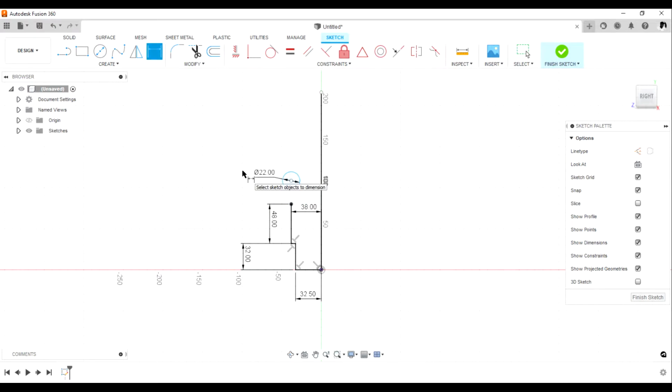Though the diameter of the arc is 22, it still falls in the section where the diameter is 76. So just draw the circle, then add a couple of relations so that it is fully defined. Then you add a line on top of that circular region. The line there was roughly 10 millimeters. Yeah, that measurement is 10 millimeters. This still has a diameter of 76.